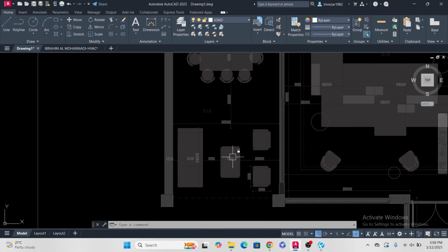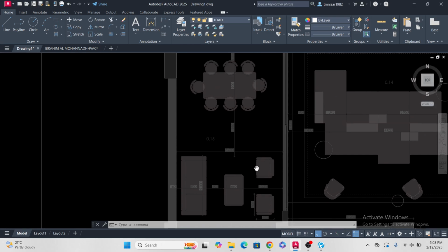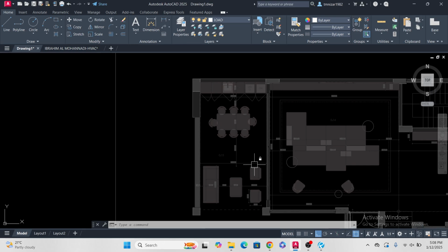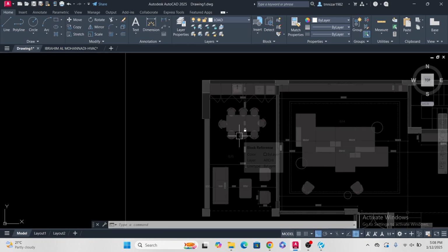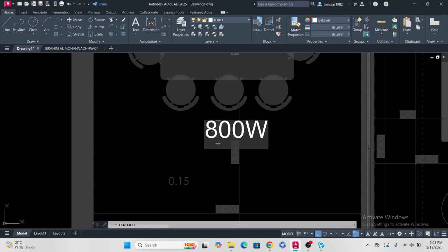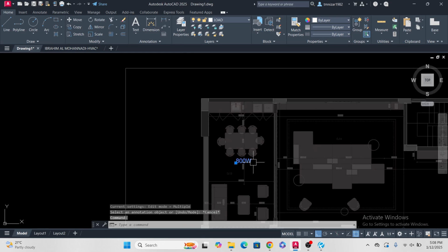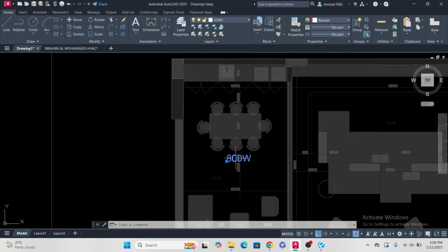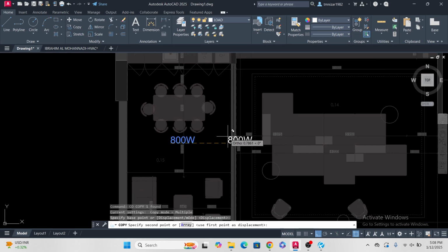And here we can use sink light, just small lights, 4 and 4. This is a villa, so they need some luxury type. So 8 by 2, 10 to 12, and here 16. So 16 lights, and I will consider each light 50 watts, with the LED type. So 16 meaning around 800 watts. Let's put 800 watts here. The spotlight maybe 25 watts will come, but for now we consider 800 watts, 16 lights.